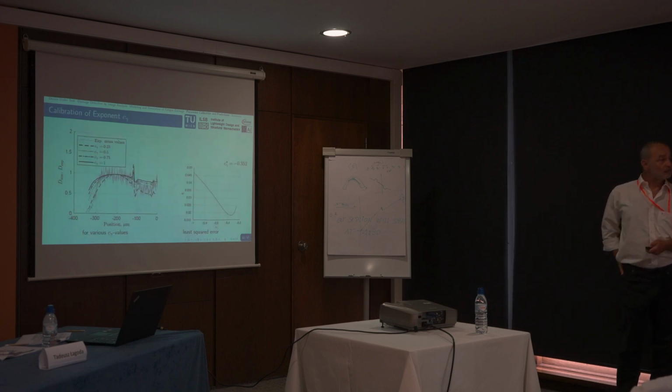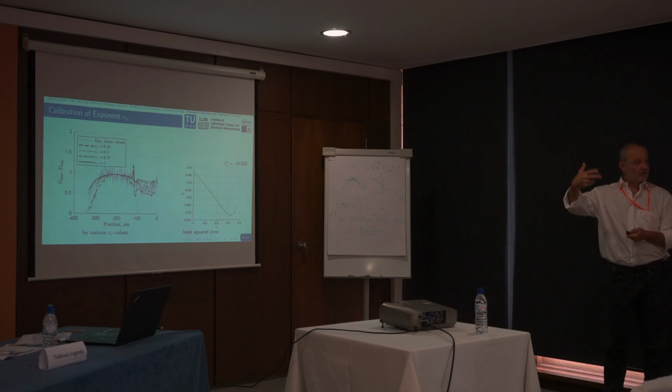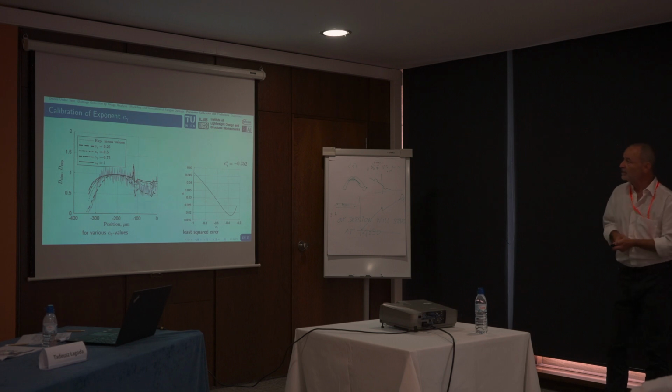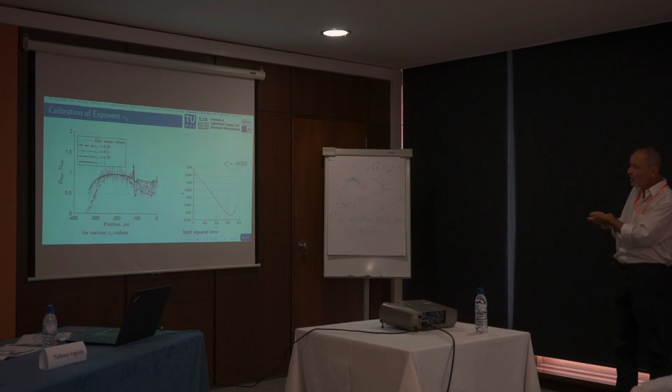So what's now the value of this fatigue exponent? You see here again the gray. This is now the mean over the 4 different experimental results. So the noise is reduced because of the mean, but it's still there. And you see 4 different curves for different values of this exponent. So depending on the exponent, you can bend it more.